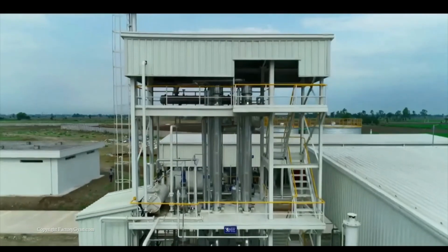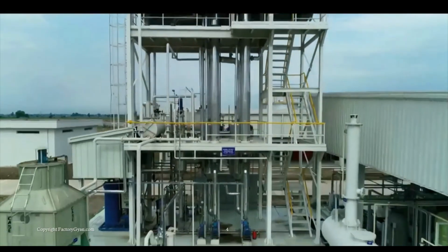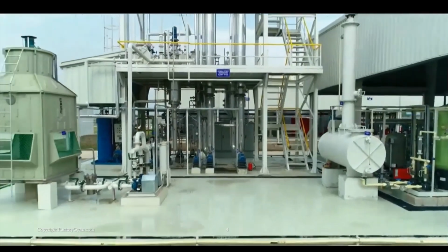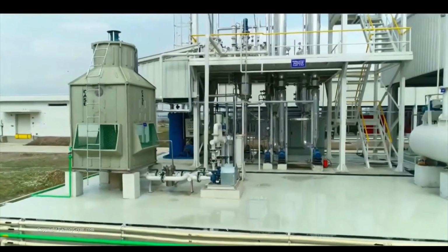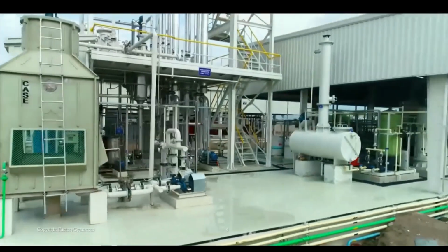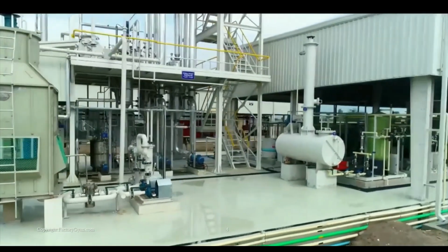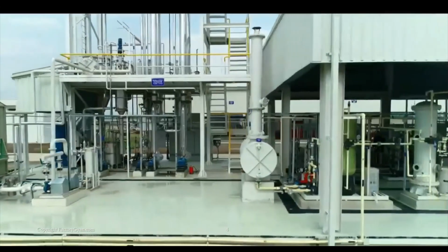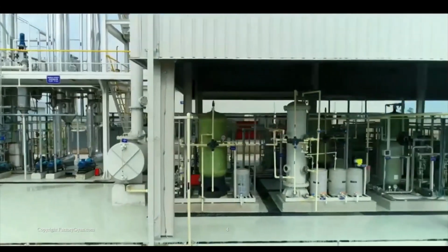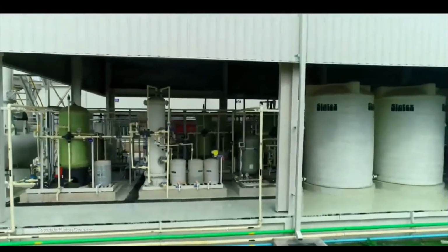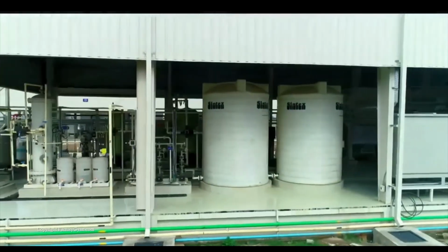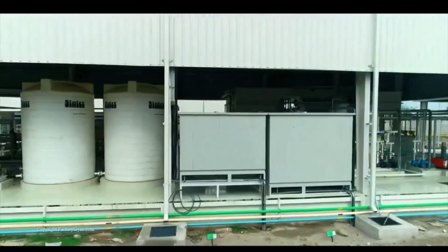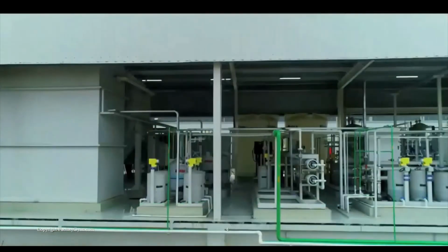This is another utility area. This looks like a wastewater treatment plant, and this looks like a zero liquid discharge plant, where they will be first passing the wastewater after treatment, first through the RO membranes, and then they will be evaporating the complete wastewater. So this looks like a zero liquid discharge. Looking at the components, yeah. So let's look at it in more detail.